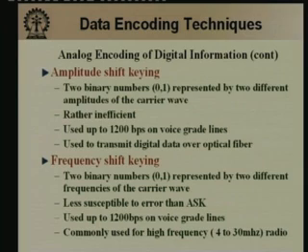More common is the so called frequency shift keying, and in frequency shift keying we use two different frequencies for the two binary digits 0 and 1. This is less susceptible to error than amplitude shift keying, and again it sends up to 1.2 kbps on voice grade lines and is commonly used for high frequency radio.